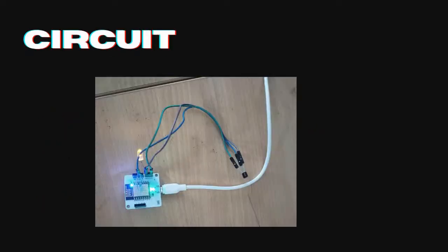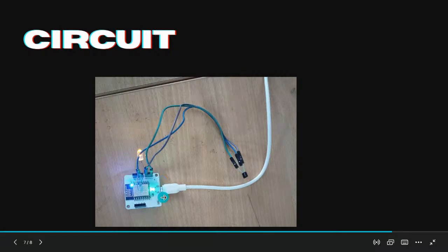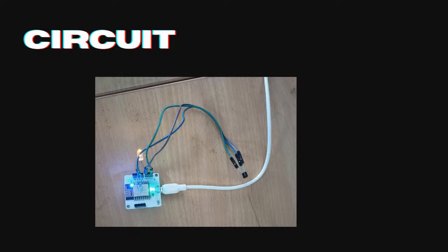Okay, these are the connections of the hardware. So how I have connected it: I have connected this Bolt Wi-Fi module to this LM35 temperature sensor. These connections I'll also explain, and I also connected an LED, and this USB cable is to give the power supply to the Bolt Wi-Fi module. First of all, we have to connect our Bolt Wi-Fi module to our local Wi-Fi. This you'll get to know from the Bolt docs. That is very easy. And later, how to connect this temperature sensor.